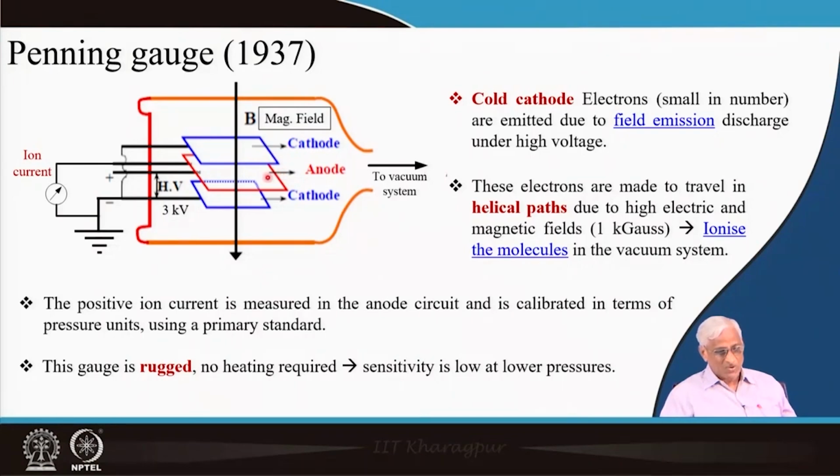Okay. So, this anode is connected through an insulated bush here, which I have not shown, but there will be an insulated piece here. This collector terminal will be insulated from the body. If it is glass, of course, they are insulated anyway, but otherwise you have to insulate this body. That is connected to the positive voltage, which is a high voltage of 3 kilovolts. This is a ring type of electrode, and there is an axial magnetic field perpendicular to these cathodes. So, now where are the electric fields? The electric fields are like a basket, a top basket and a bottom basket, because the anode is a ring and the plates are there in between the ring.